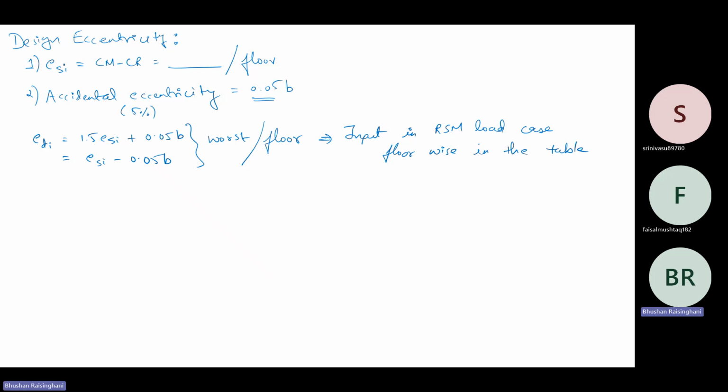So you have to control your stiffness in a manner to achieve these criteria as mentioned in the IS code, which are prone to earthquake resistance. Otherwise, there is always a chance that the earthquake may overpower the resistance of the elements and cracking will happen.